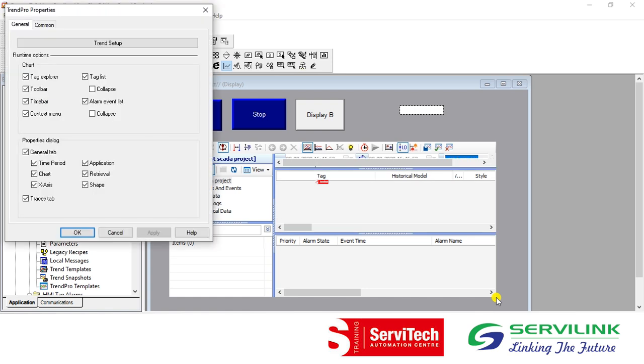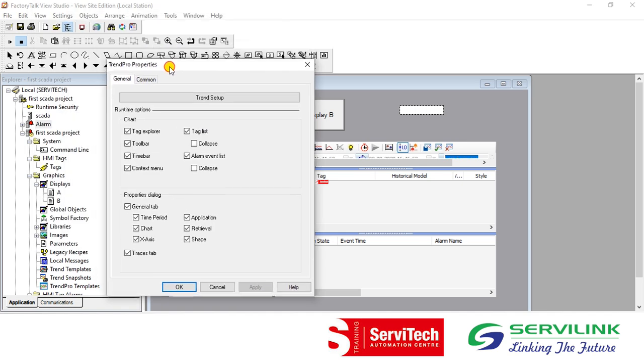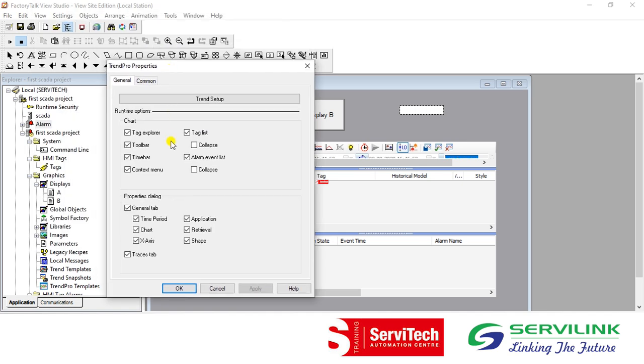This type of graph will be drawn, and after creating the graph you can see the Trend Pro properties. Whatever toolbar and other things you want to see on your graph, you can check, and you can uncheck any toolbar you don't want. After setting these options, for setting up the value that will be shown in our graph, we have to go to the trend setup. So just click on the trend setup.